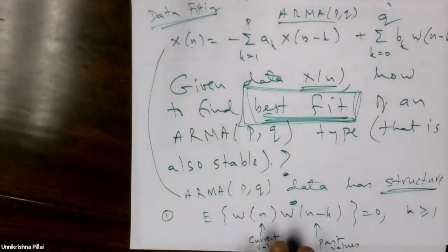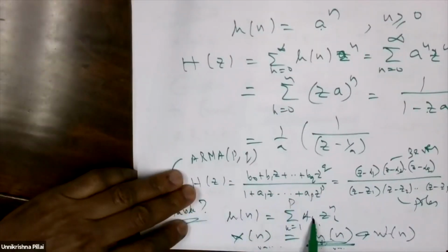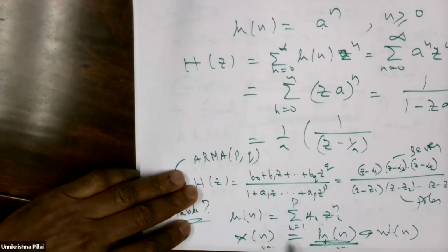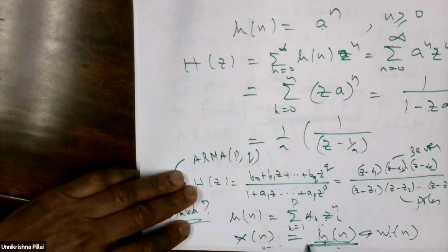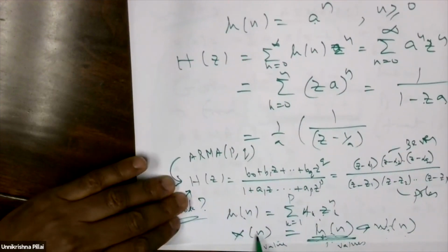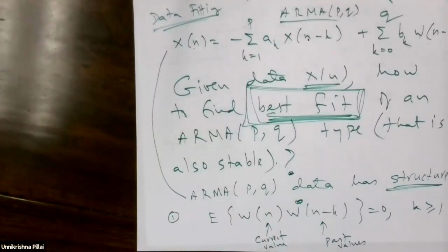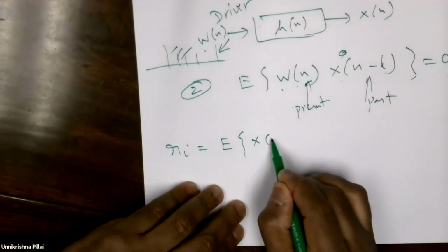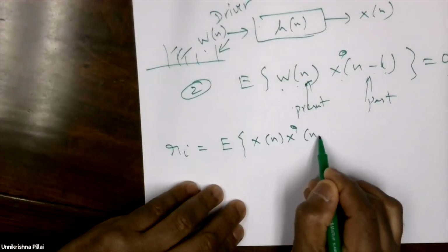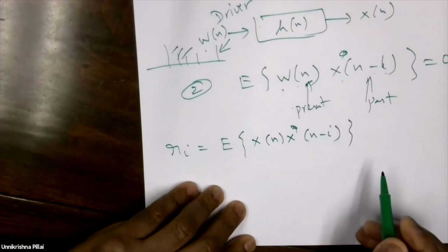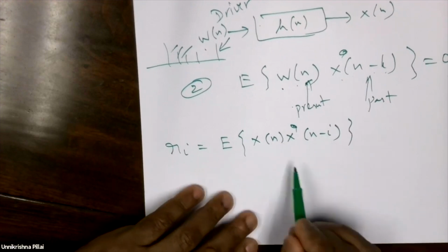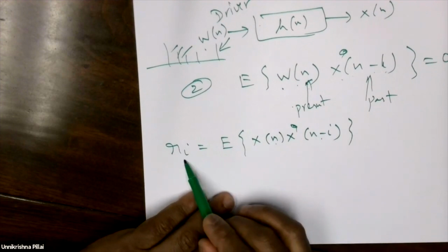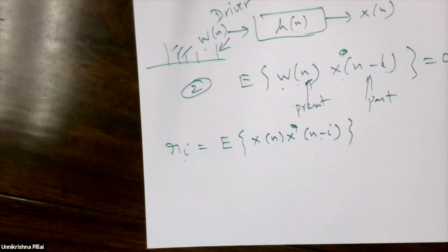Because I can write the system like this, if the input is wide-sense stationary, you can see the output is wide-sense stationary because of this relation. I'm going to assume that the input is wide-sense stationary. Consequently, the output is wide-sense stationary. So I am calling it T1 minus T2. That's the reason I am writing it like this.